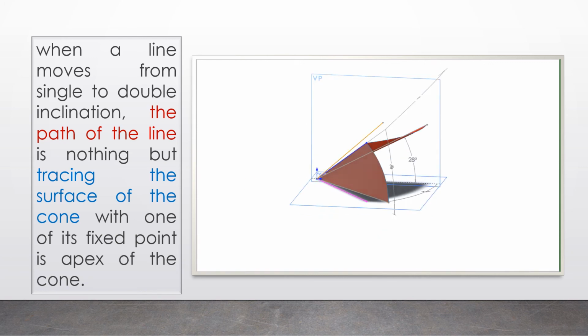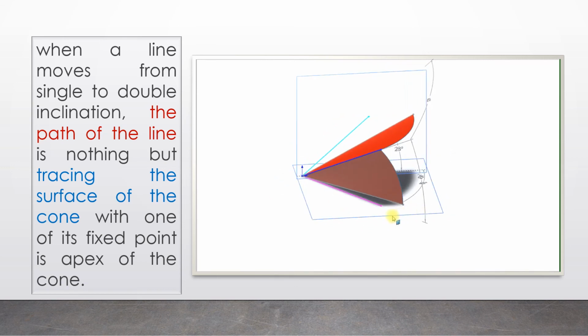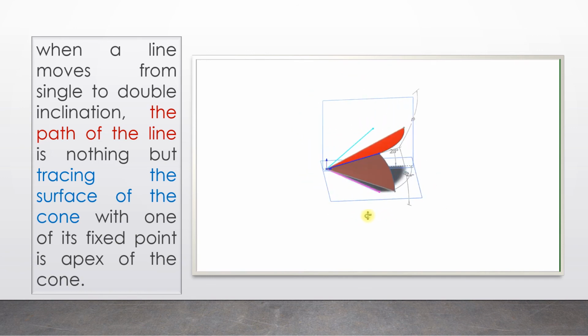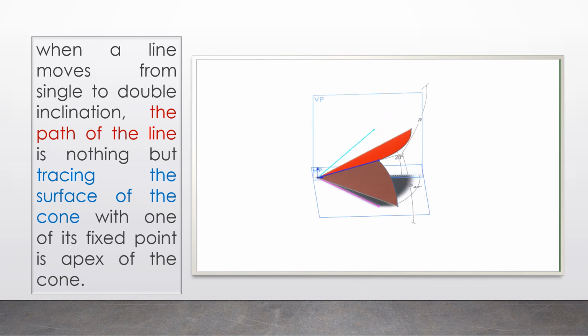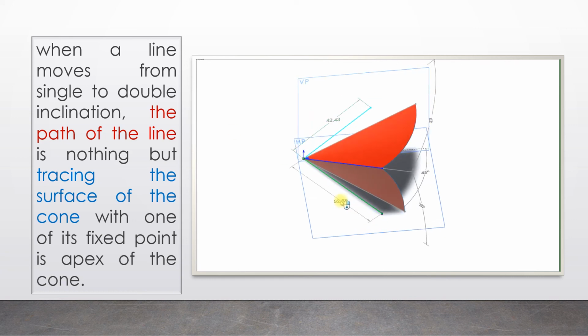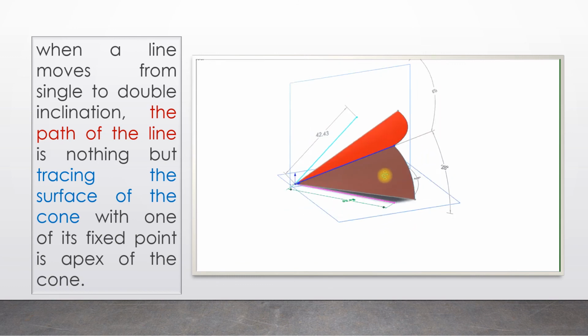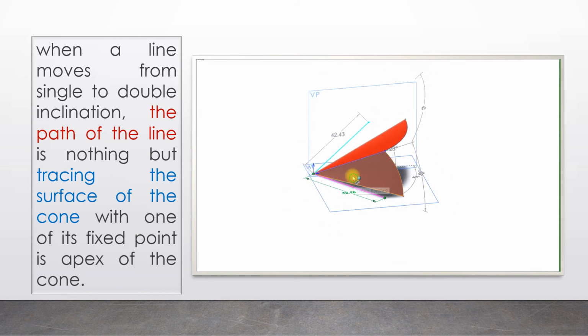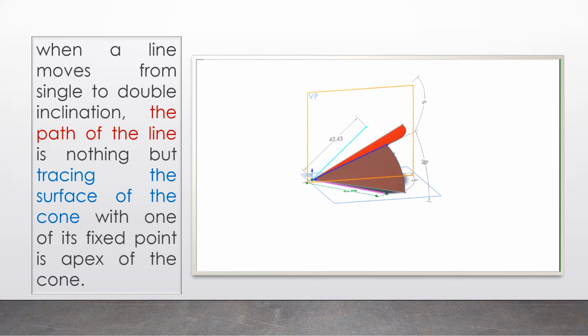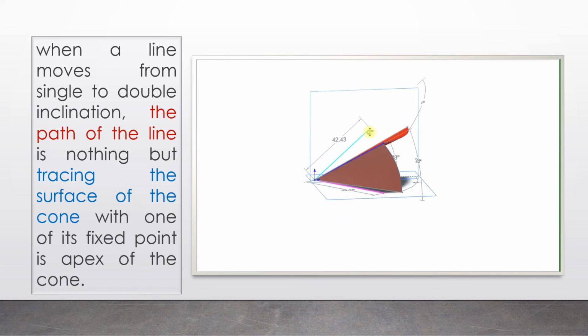And its projection B3, the front view of that line, we call A dash B3 dash in elevation or in front view, that is the shortened line. So AB3 is actually the true length in space, but when it is projected in the vertical plane, because of the conventions in orthographic projection, it looks shortened. So A dash B3 dash is the shortened length. Actually the original length is in space, it is the true length.